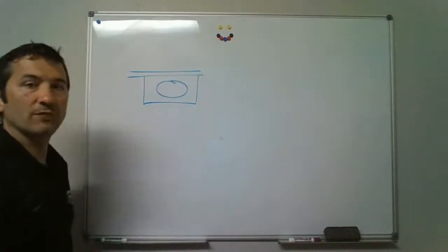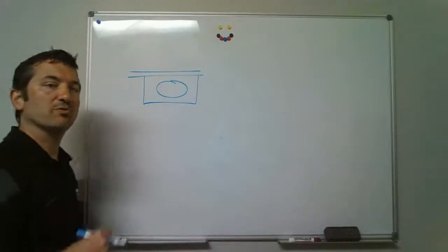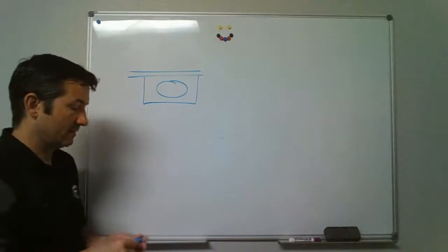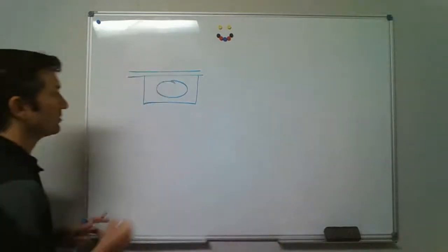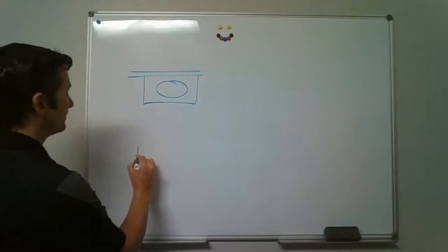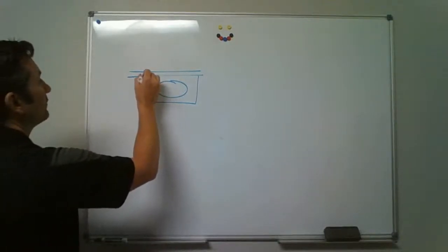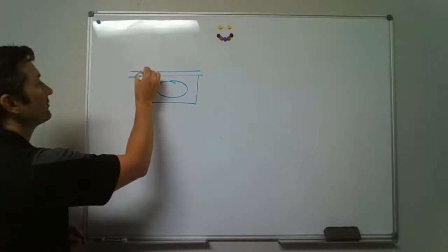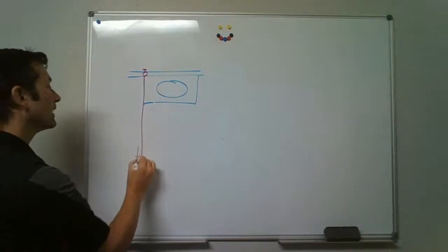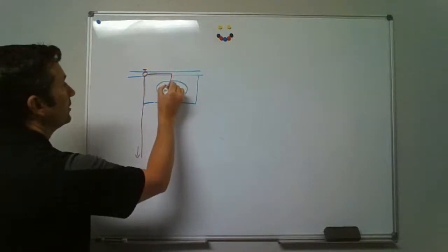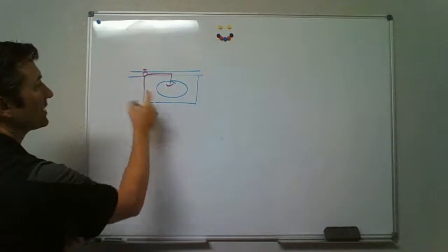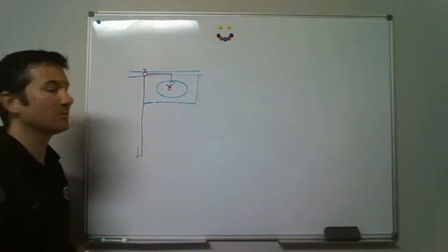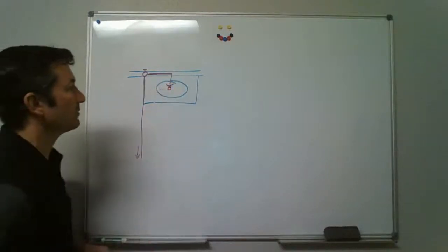So you all have already been over some of the first lessons, looking at this and trying to draw the bird's eye view drawing of that. I might have shown you the lavatory and said, take the drain out in this direction. And if I did, you would have put a vent over here on the side. Maybe I told you to put a clean out in the back, so you might have drawn the symbol for the clean out. Drew the drain going out in that direction. You armed over the wall, and the reason we stayed over to the one side for the vent is to stay out of the way of the electrician who's going to put his light fixture directly above the bowl. So we armed over, out, and then the symbol for the P-trap.